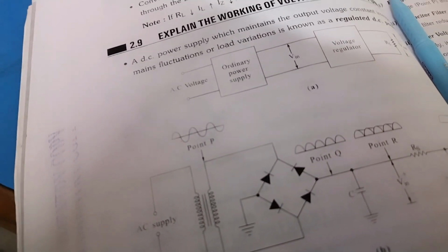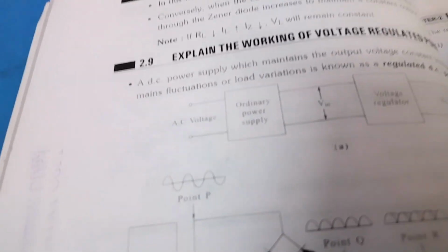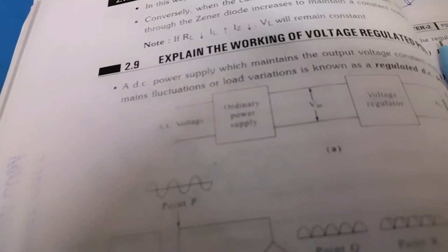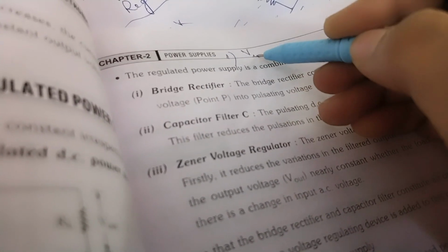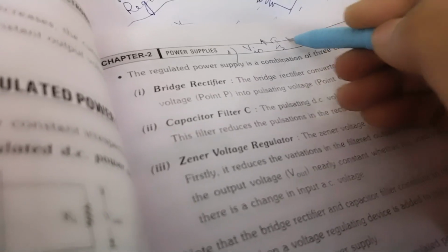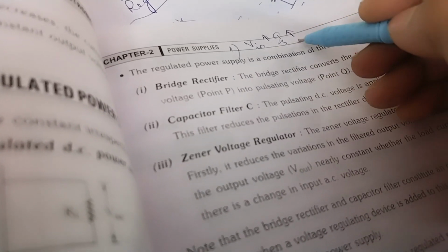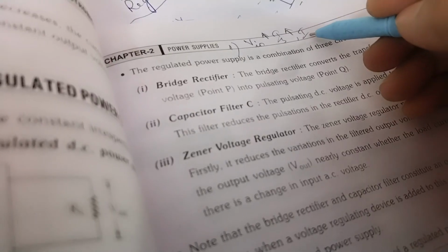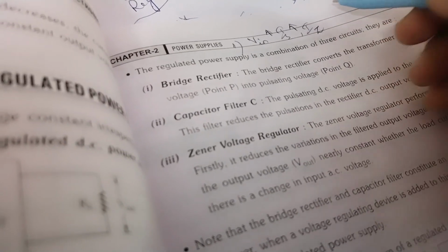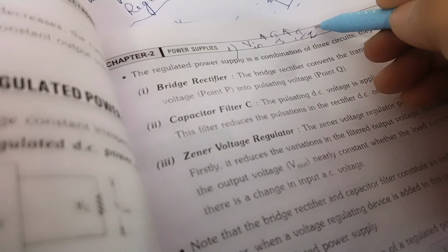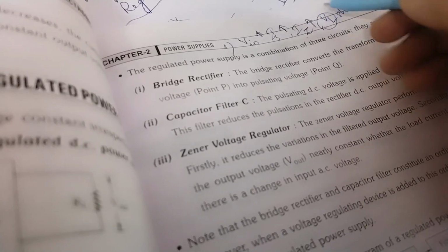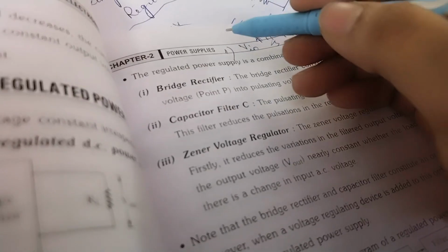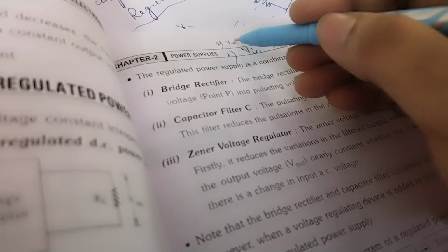So we have just 2 cases. In the first case, input voltage varies. Within a single line I can conclude that. If the input increases, then the series current IS increases. If the series current increases, then the IZ current should increase and VL should remain constant, because IL should remain constant. That is the first case.